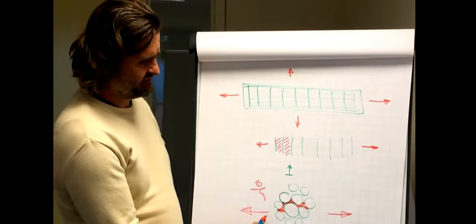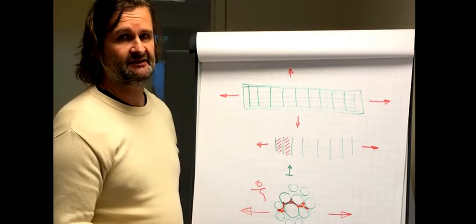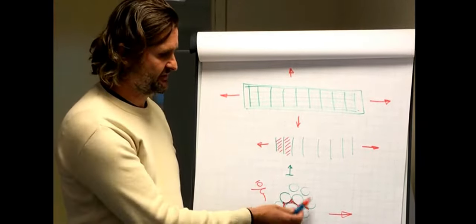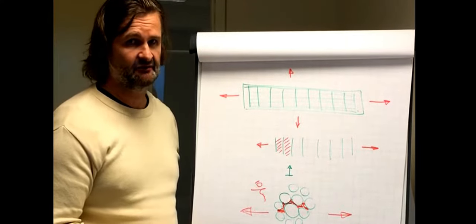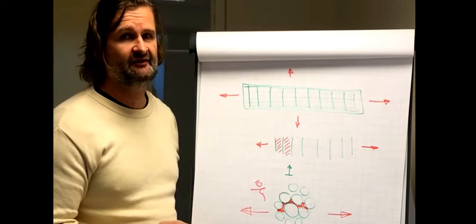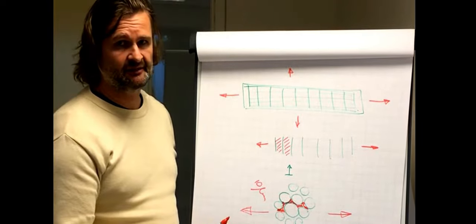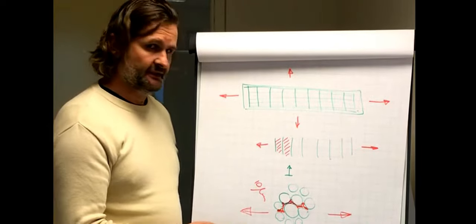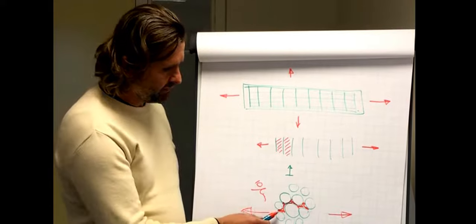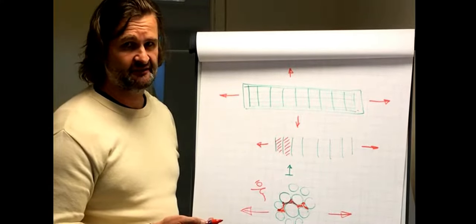So if I increase the flexibility of my resin from 2 to 6%, in practice that would mean an increase of the flexibility of the entire layer of 0.1 to 0.2% or 0.15 or something. It's very little, because most of the makeup of the layer is glass fiber, and that is high modulus. Another disadvantage of getting more flexible resin is that the temperature resistance decreases with it.